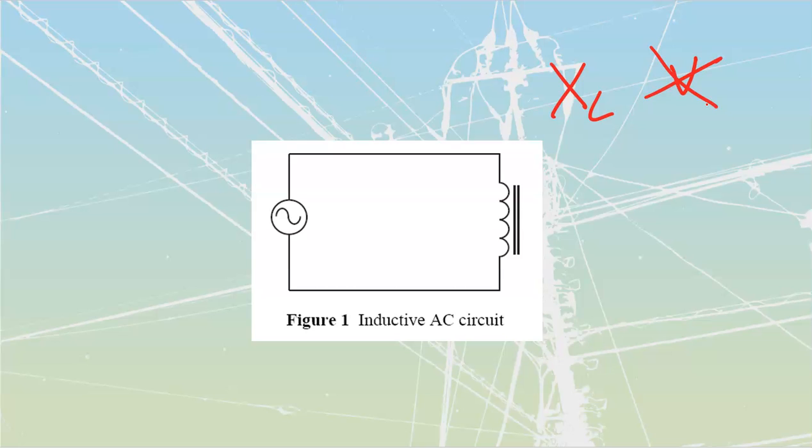Frequency. The frequency makes a big difference to us, because if I double my frequency, that means my waveforms, instead of looking like this, are now going to be looking like this. That is a far, far more steep side to it, which means my rate of change is also going to be doubled, where it's going to change way, way faster. So if it's going doubly fast, yet I still have the same amount of peak voltage, then I'm also going to affect the amount of current that I'm going to have going through it.